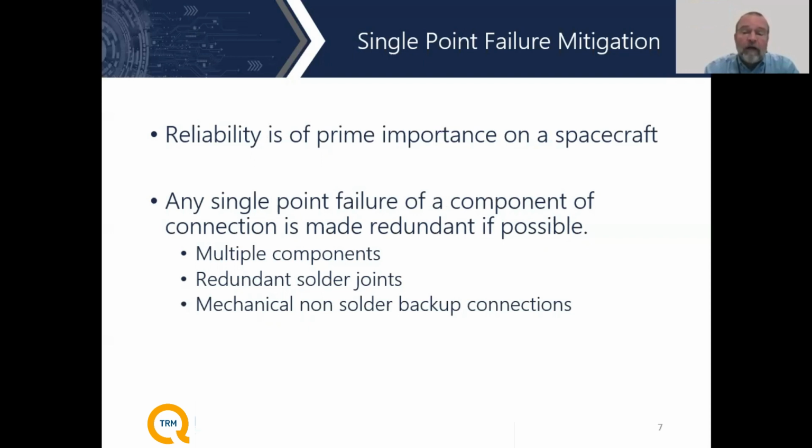And really, the functionality of these parts is what's most critical for the mission. A lot of the parts that we build for spacecraft are part of the local oscillator signal distribution networks. And if you lose the local oscillator, you lose the entire bank of up and down converters. So these are mission critical parts. We have to make sure that signal continues to be distributed.